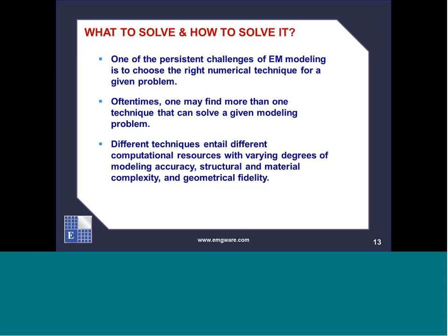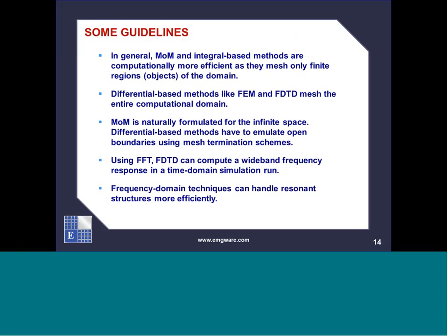Some guidelines that basically can help us to choose the right method: first of all, it depends on what tools you are using. For example, most commercial tools that are available in the market are usually based on one particular technique. For example, HFSS from Ansoft is based on finite elements. So for 25 years they have been promoting finite element as the method of choice, as a solution method. CST Microwave Studio is based on FDTD.